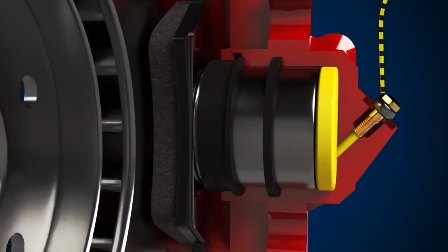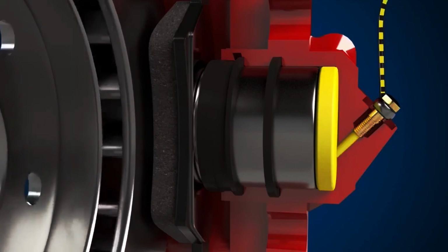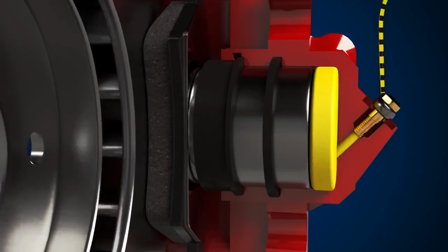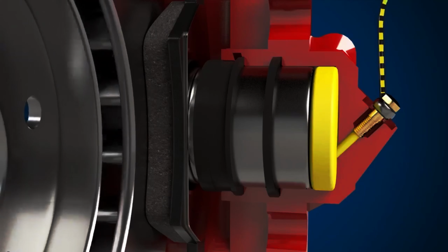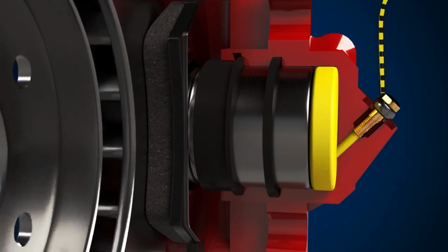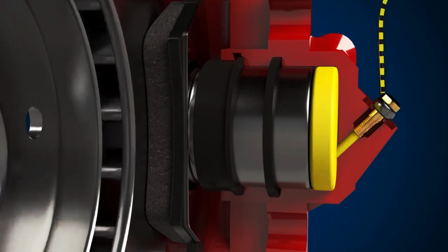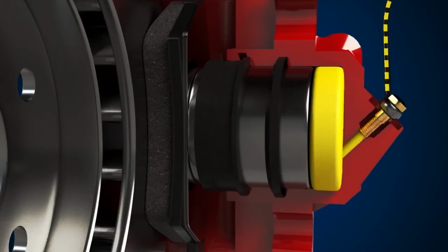The brake pedal is pressed and pressurized hydraulic fluid enters the caliper body. Hydraulic pressure pushes the piston out, first forcing the inner brake pad against the inside of the brake disc. As this happens, the inner piston seal deforms. Now, the inner brake pad cannot travel any further, so hydraulic pressure forces the caliper body back along the slider pins, pulling the outer brake pad against the outside of the brake disc. When the brake pedal is released, the inner piston seal reverts to its original position, withdrawing the piston.